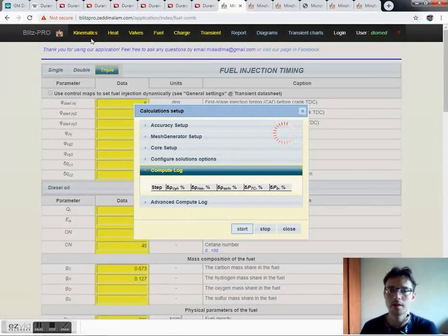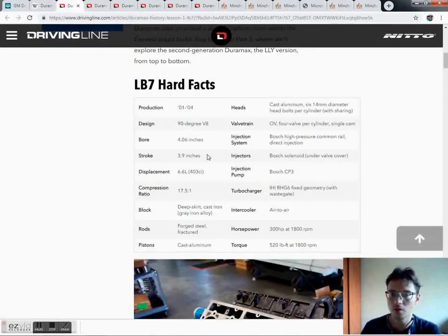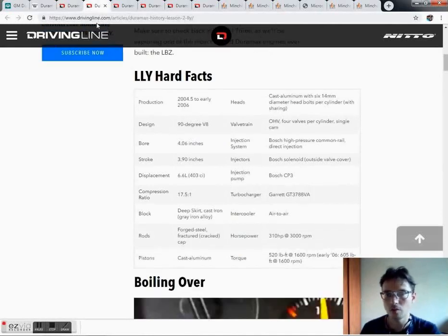And yeah, as we see, the progress of this engine was marked with a continuous rise of the fuel injection pressure, and also the first injectors were solenoid injectors, which allowed up to 3 fuel injections per cycle, maybe 2, pilot and main.